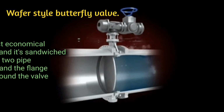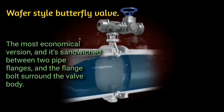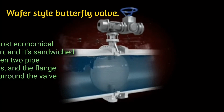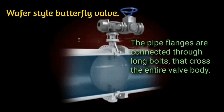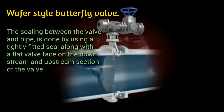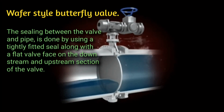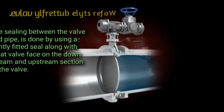Wafer-style butterfly valve, the most economical version, is sandwiched between two pipe flanges, and the flange bolts surround the valve body. The pipe flanges are connected through long bolts that cross the entire valve body. The sealing between the valve and pipe is done by using a tightly fitted seal along with a flat valve face on the downstream and upstream sections of the valve.